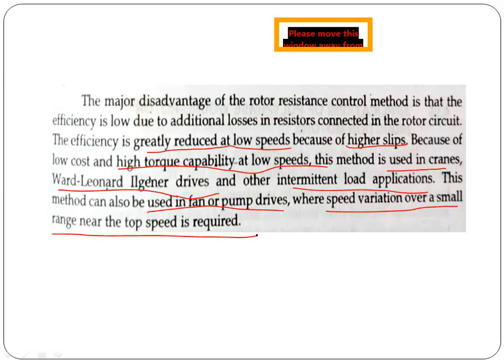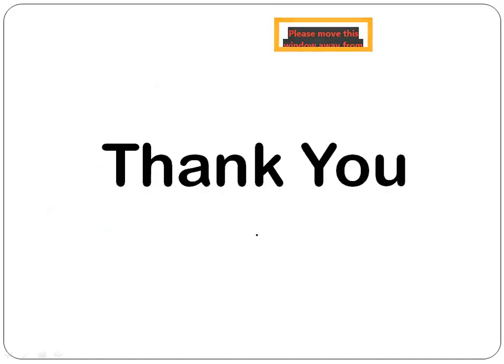So to recover from this low efficiency problem of rotor resistance control method, there is another method, that is the slip power recovery scheme, so that we can use the power which is lost in these external resistances, and that slip power can be recovered. That scheme is also there for reducing this efficiency problem. So that is all for speed control of three-phase induction motor.